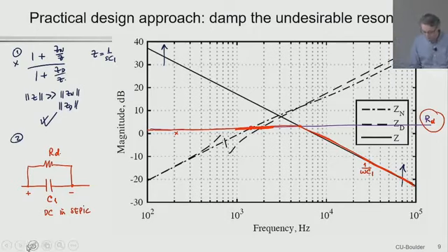So you can envision that that's going to be very simply consisting of adding a CD capacitor in series with RD. Okay. So what is going to be the impedance now of this combination when we add CD, and how should we choose the value of CD to produce that effect?